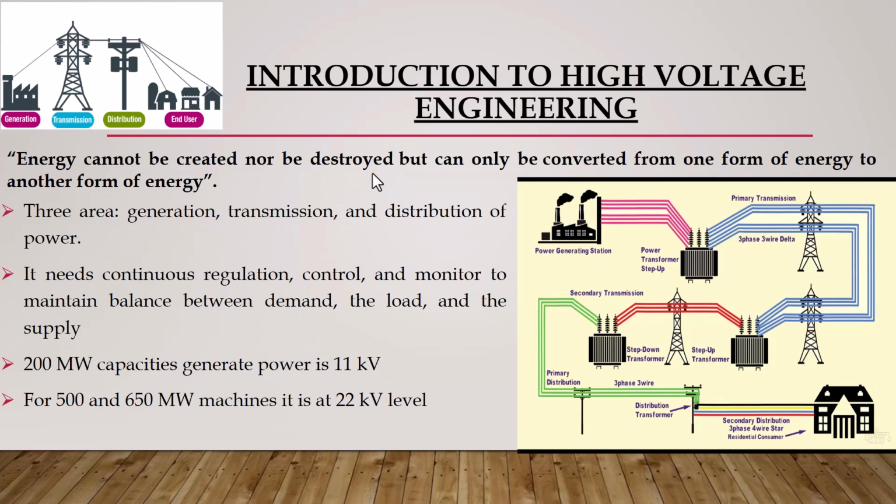And here's a point I want to emphasize. Higher power doesn't necessarily mean higher generation voltage, but rather, as power level increases, we choose generation voltages that balance equipment size, insulation requirements, and efficiency. Or to put it another way, we don't generate at very high voltage directly, we generate at moderate levels that are practical for machines, and then step them up for long distance transmission. That's one of the first lessons in high voltage engineering. Understanding not just what voltages are, but why they are chosen that way.